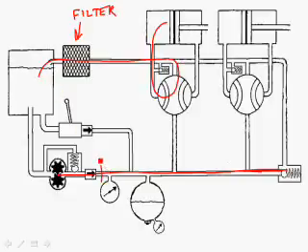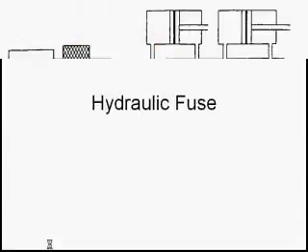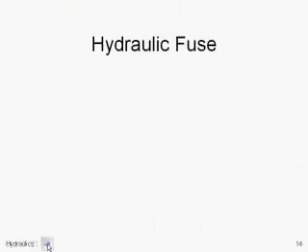Now you could put a filter in a lot of places. In cars, they usually put the engine oil filter right after the pump. But in a hydraulic system, most of this fluid here is getting pushed back to the reservoir, so it's pretty easy to push fluid through a filter. It takes the things out, just like in a car or a small airplane piston engine oil system. It takes little tiny pieces of metal out so you don't keep circulating the chunks of metal inside and wearing things out. So it'll last longer, won't break as often, it's more reliable.